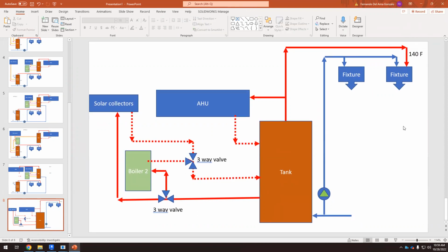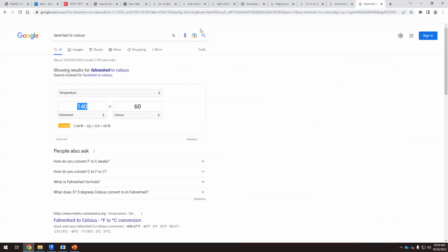So if you open the hot water in the bathtub or in a shower, after a few seconds, you get burned, okay? So you can't stay for 1 minute under 140 Fahrenheit because it's dangerous. So why do we need this? Because we have to kill the famous Legionella, whatever. This is the bacteria.